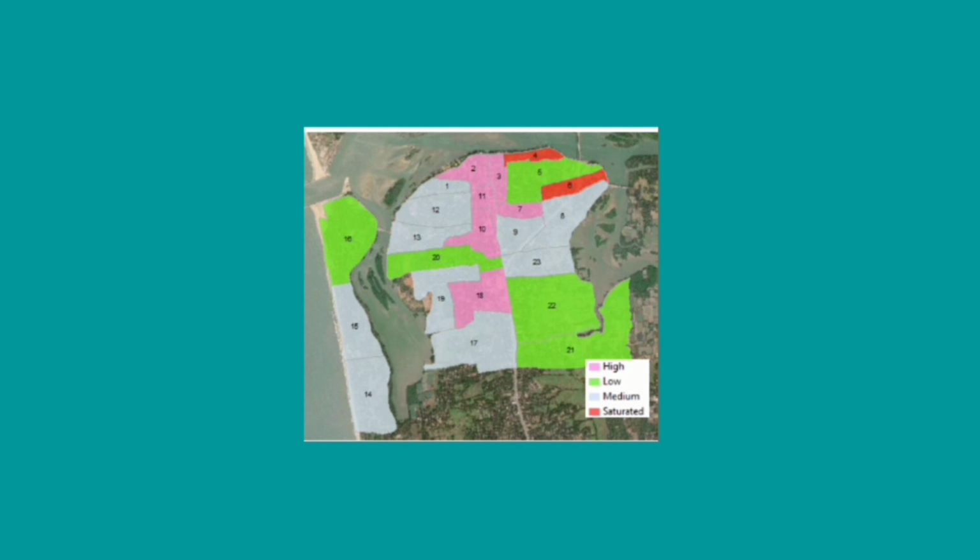So in a nutshell, once you have forecasted the population by any method, there will be two criteria that will be deciding the distribution of your population into wards. The first one is the current density of that area, and the other is the growth potential of that area, right?